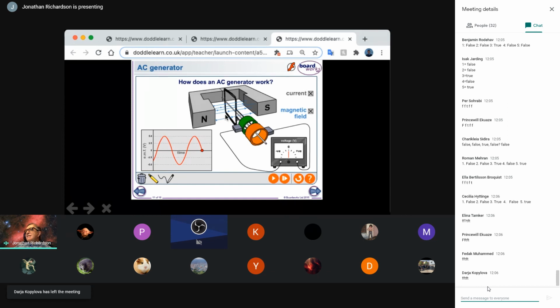As you can see, this is outside, this is outside, so the resulting voltage just here is 0. And if I rotate this through 180 degrees, I go through the maximum, so this is moving up through this field, down through this field, keep going again to the top, and again we've got no cutting through the magnetic field lines.